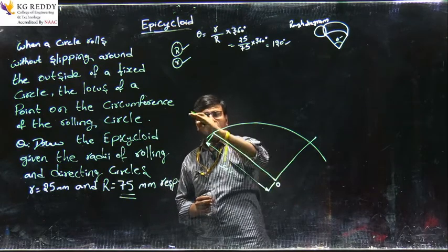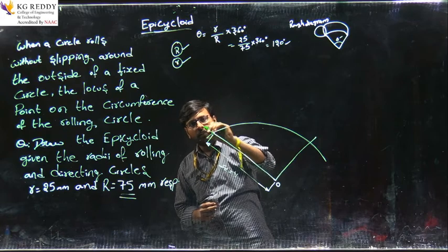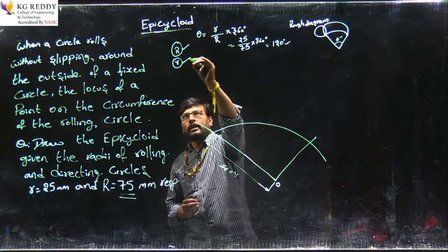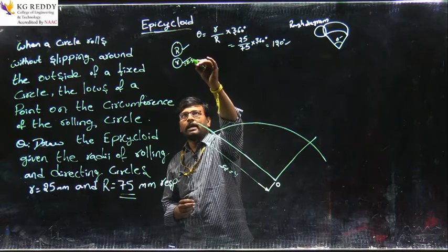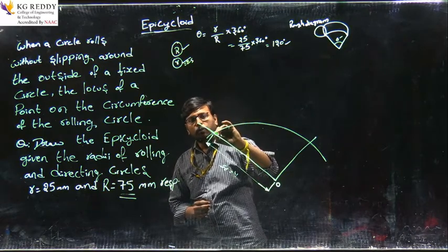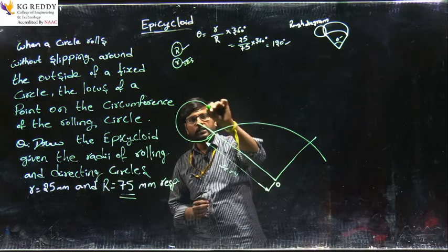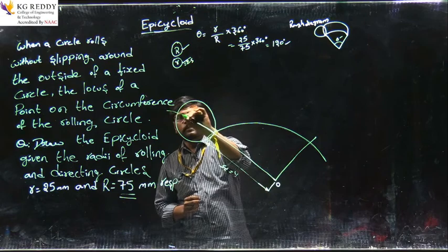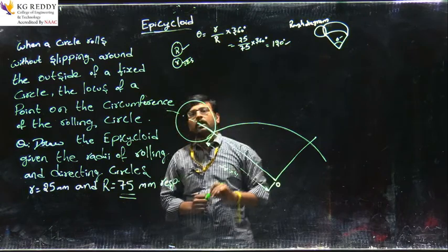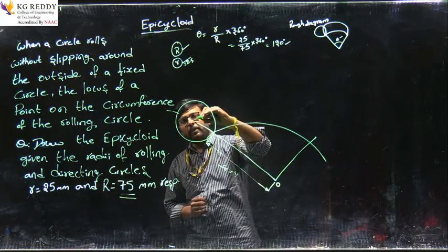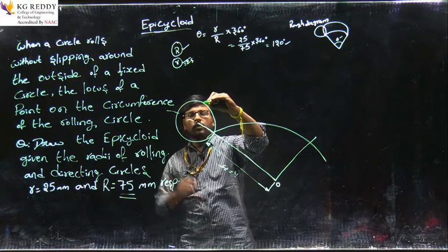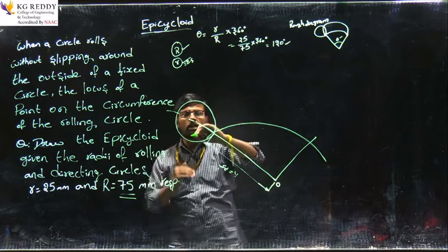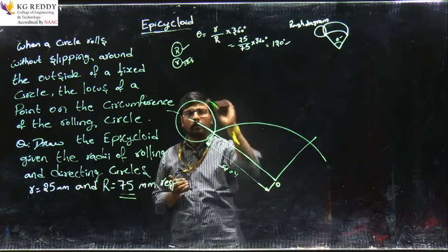Corresponding to this line, I extend it by 2.5 centimeters, because the roller radius is 25 mm, that is 2.5 centimeters. This is the vertical axis, and I take a perpendicular to it as the horizontal axis, which we use for the division of this circle.